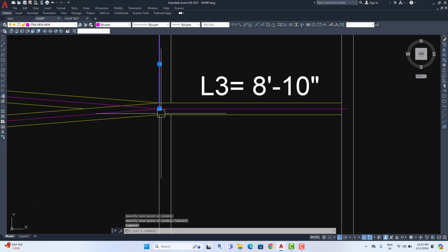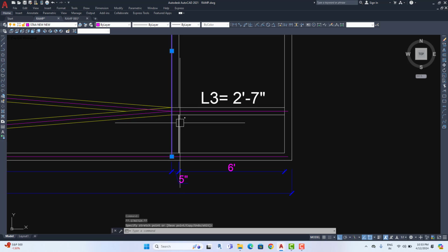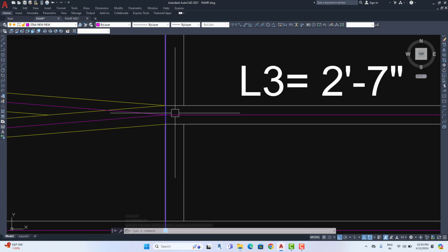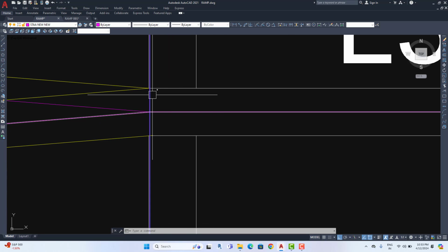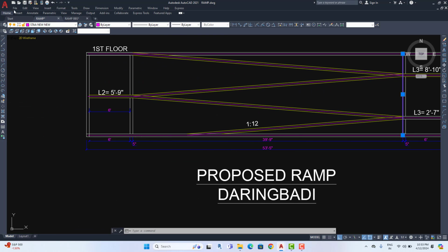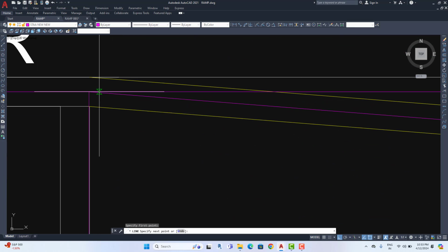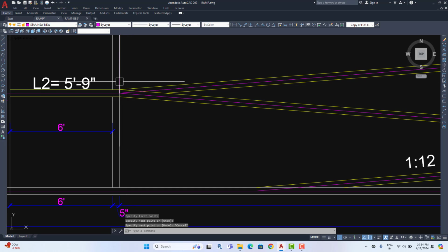When we make the structural drawing in AutoCAD, at that time I'll make this my column. But if I'm going to transfer to Staad Pro software, then all the joint points must be a single joint point. So here I'm going to make a center line, and here also at the joint point I'm going to make a center line. All joint points should be a single joint point.